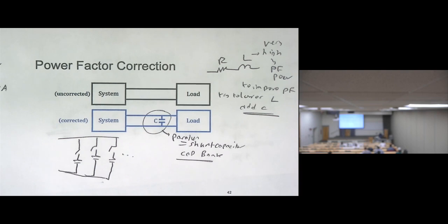So if it is at half capacity and we notice the power factor is 0.75, then let's turn on one capacitor. Then the power factor is 0.8. No, we still need more, so let's turn on another capacitor. Then 0.9, that's enough. We don't need to add all of these capacitors. Why don't I want to add all of them? Because this will make a negative impact on the grid. So I need to keep my power factor within the 90s.